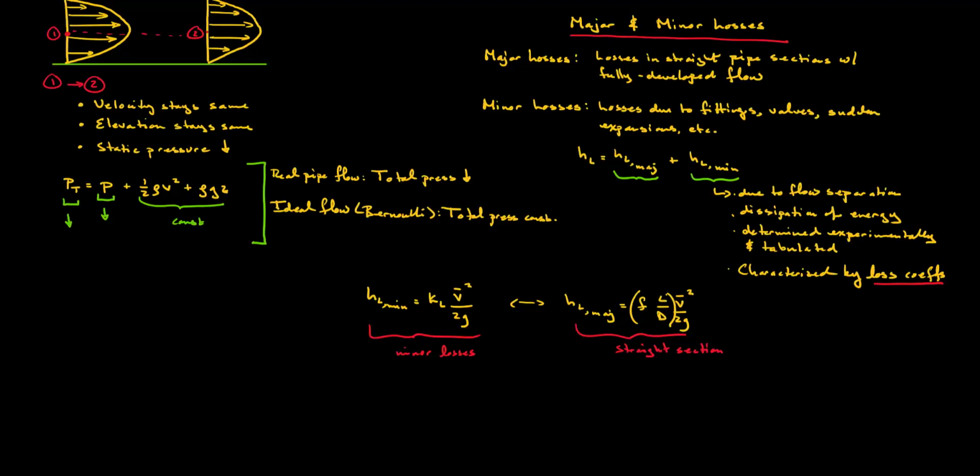And what we found experimentally is that these loss coefficients seem to be only functions of geometry. Or rather, we should be a bit more specific, and they are much stronger functions of geometry and less so of Reynolds number and surface roughness. Whereas, as we know, the friction factor is a function of Reynolds number and surface roughness.